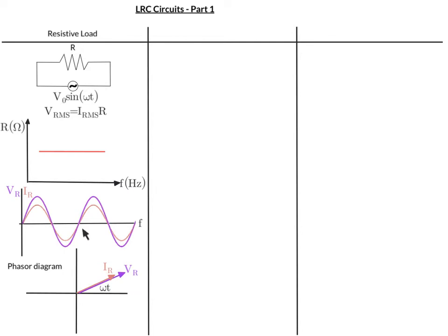Now, we're going to see later that it's hard to draw these diagrams. So there is another way of representing these sine waves, and that's called a phasor diagram. So here we have the current that is in phase with the voltage across the resistor. That's what we were indicating by the phasor diagram, that both current and the voltage are in phase with one another. And as they fluctuate here, they will basically rotate in this coordinate system. So here we have the omega t. Omega, remember, is 2 pi times the frequency. There's the same type of rotation here that there is oscillation over there.